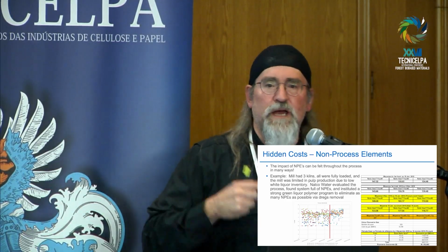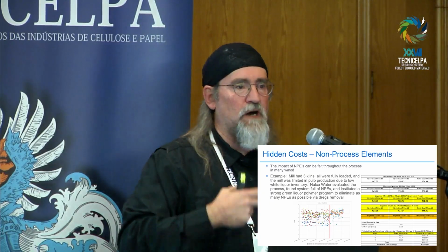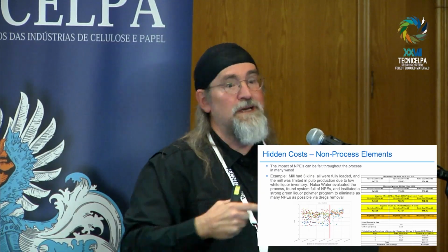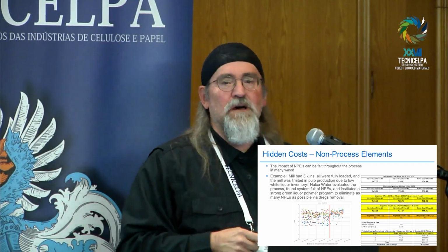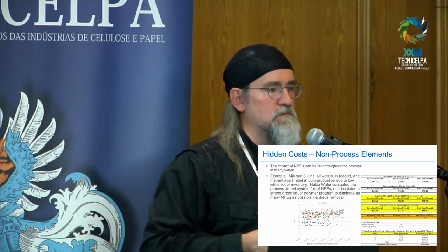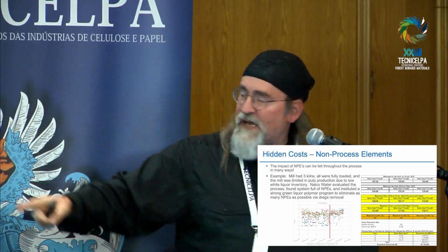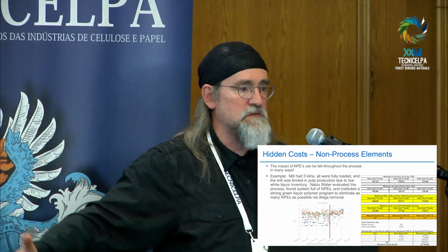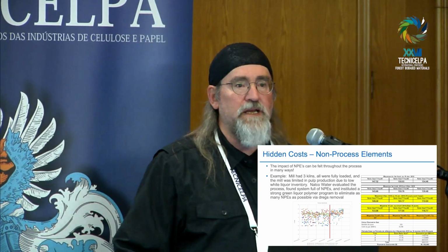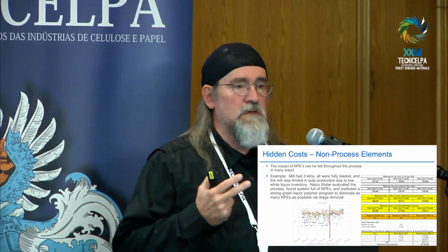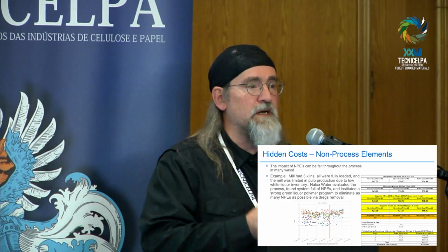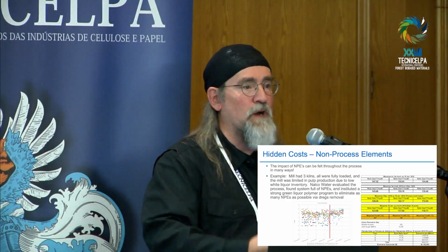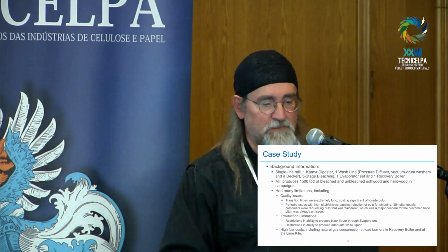So we went back and we optimized the clarifier. We changed some things around there, how they were balancing flows and how they slowed down the movement of their stabilization tank, like I showed earlier. Okay, all we did was get the dregs out. That's all we did. And we saved over $1 million in kiln gas because the solids came up by themselves. Okay, I didn't need a chemical. I needed to work on the right problem. Okay, still a liquor chemistry issue, but make sure you've done enough digging in to know what the problem actually was and solve that.